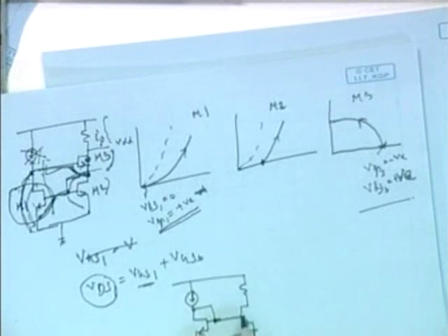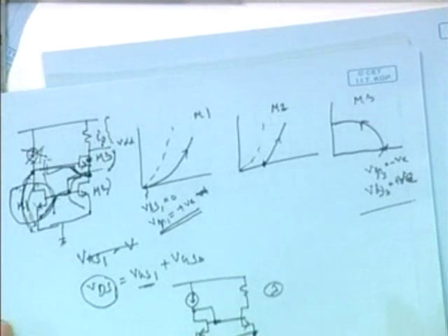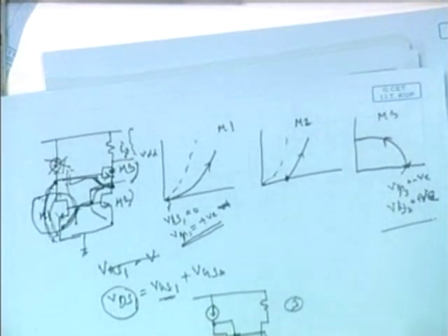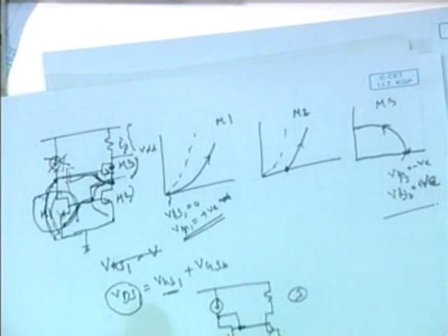So now, using the same principle or same logic we have used, these 2 points are tied to the same voltage, VDS of VDS1 and VDS2. So though we have finite lambda, we can have very good accuracy using these circuits. So this is the Wilson current mirror, or you can say modified Wilson current mirror.